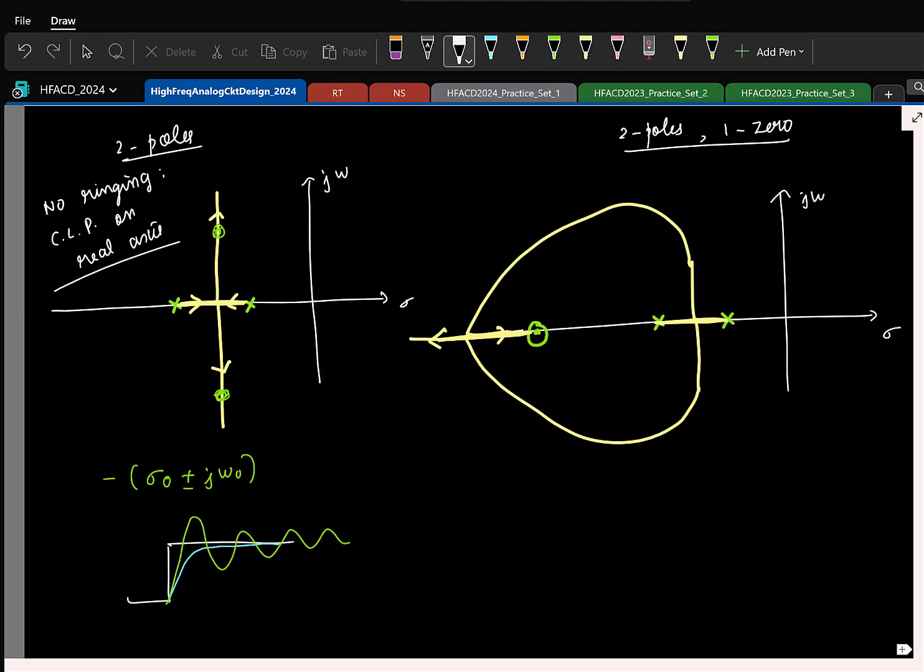Cool. So now let's up the ante. Let's take 3 poles. Does the ringing in the step response, if I increase the DC gain, first increase and then after some value of DC gain, start decreasing? Correct. Exactly. So for these values of DC gain, you have significant ringing. This is the direction, and after some value, which is this one.